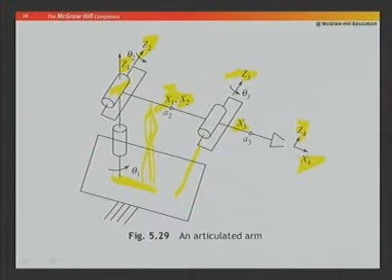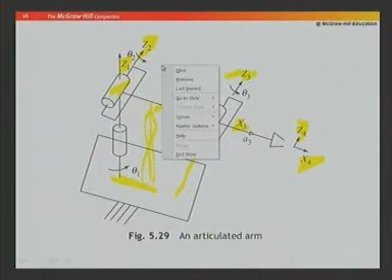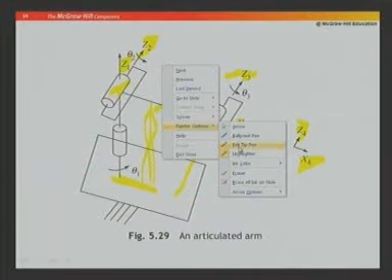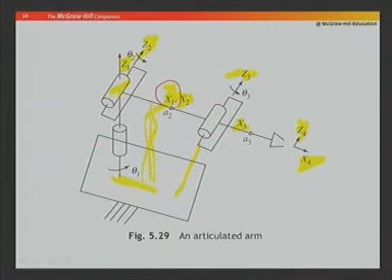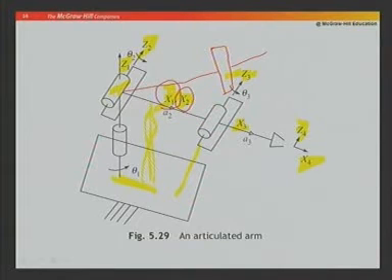Theta 1 is the joint angle between x1 and x2. So, this is my x1 here and this is my x2 here. The way the drawing is made, they are at the same location. So, at this position theta 1 is 0, but notice that this joint will move. Which means this will come after some time to some position like this. So, obviously, then you will have some value theta 1, which is a joint variable.